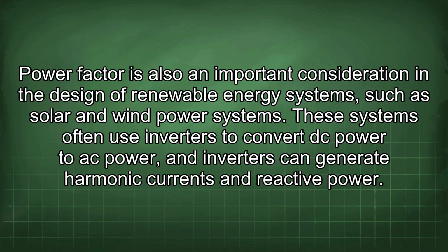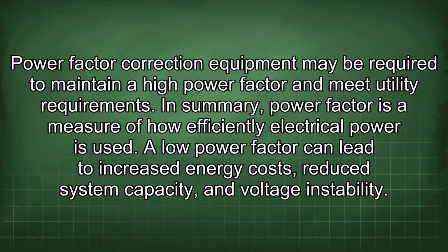Power factor is also an important consideration in the design of renewable energy systems such as solar and wind power systems. These systems often use inverters to convert DC power to AC power, and inverters can generate harmonic currents and reactive power. Power factor correction equipment may be required to maintain a high power factor and meet utility requirements.